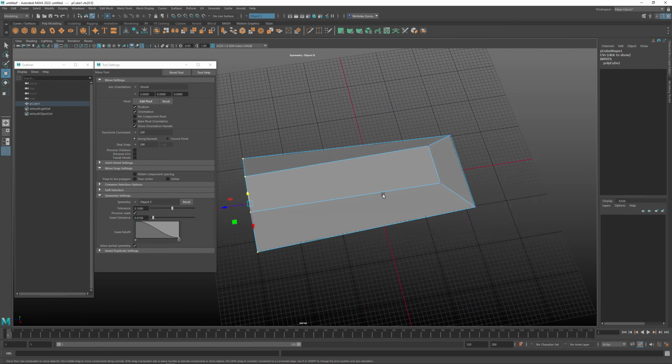this surface. So if you think of this as a 90-degree plane, as it starts to round out, we're going to get some curvature going this direction. We're going to get some curvature going this direction too. So we'll put it up one division level, and you can see this is the curvature that is starting to happen. It does some type of mathematical averaging between this surface and this surface here. And so at this level, this is the first subdivision level up. It's taken each face and divided into 4, and it's smoothed based upon the other faces around it.